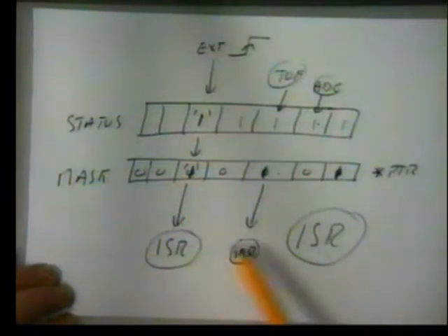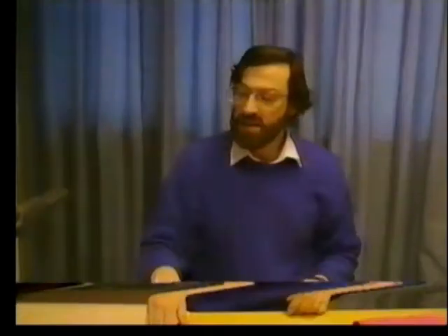This means that you also have the ability, if you wish, instead of allowing ISRs to occur, to poll them, which means that instead of using the mask to call interrupt service routines, you could just look at the contents of the status register. You could poll the status register. So if you want to use these wonderful features in the processor, timers, counters, PWM, ADCs, but you don't want to get involved in the horrendous data handling problem of interrupts, multiple functions, parallel processing with semaphores and boxes, you don't need to.